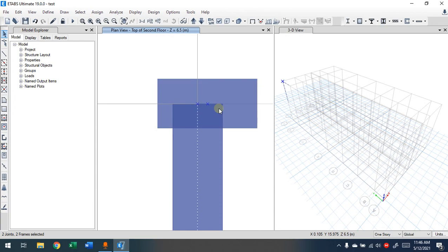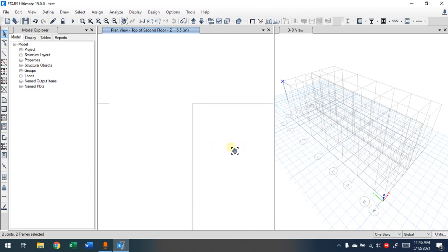in the modeling, you have to link those two joints in order for the load to transfer properly from the beams to the column, and for the moment, for the rotation, for everything to happen as we know it from the analysis of structures. This is a joint between them, so the load transfers from one joint to another joint. So if you have a case like this, you need links, a rigid link, in order to connect those two together. So this is why we need link in